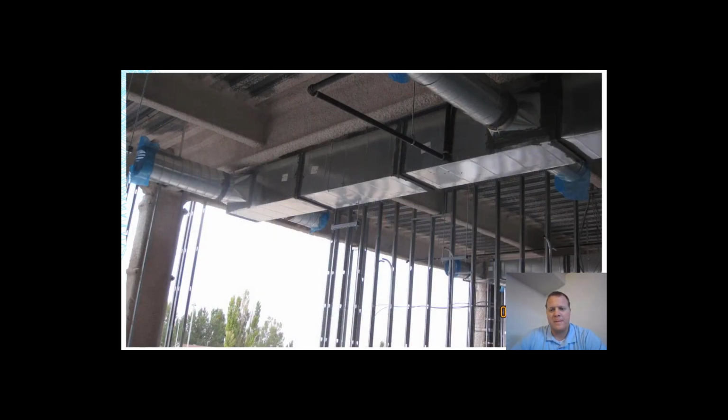And as we talk about above ceiling and that sequence, you can see this fire sprinkler line, the fire suppression line, is above this ductwork. Look how close that is to the beam. It would be pretty hard for the fire suppression contractor to get his pipe in after this ductwork is in. So generally, again, the rule of thumb is to work from the top down when we're talking about construction sequence above the ceiling.